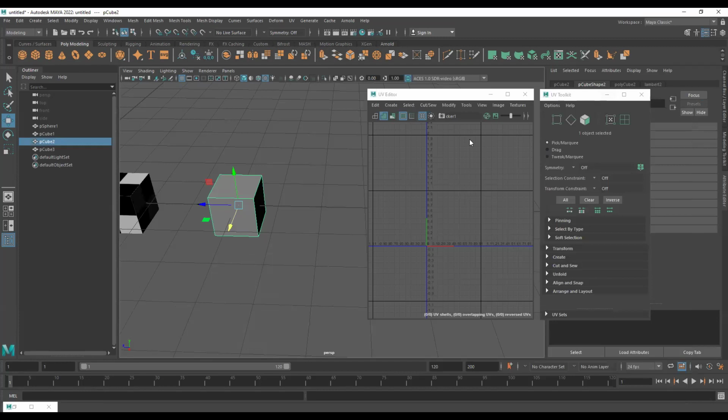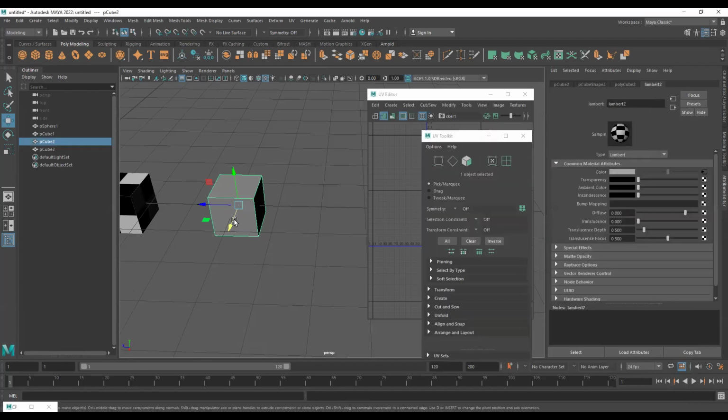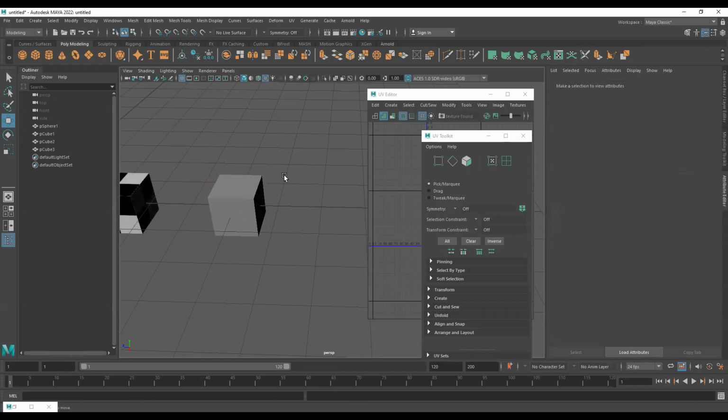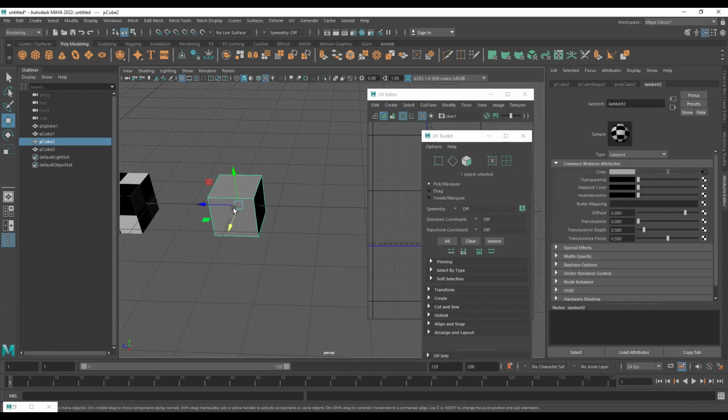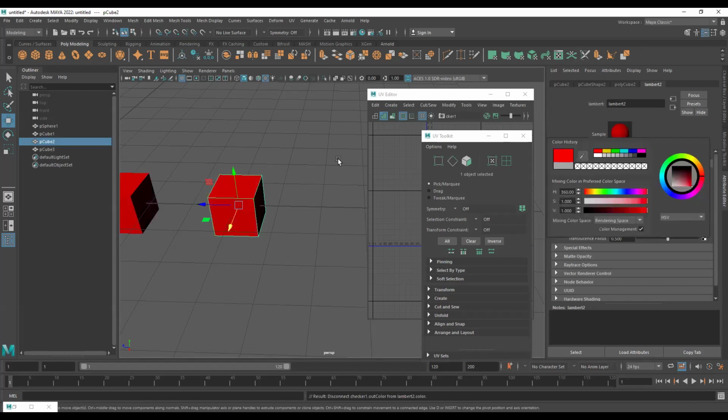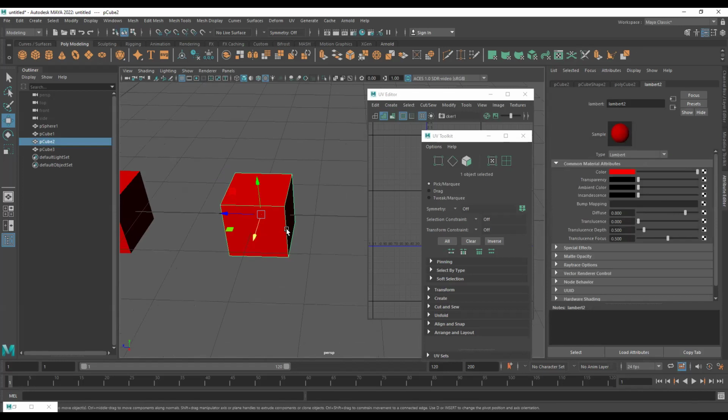Are you sure there is no material? No, you can see that the material is assigned to the selected object, of course, but we don't have any UV. So without UV, you cannot see the textures. For example, if I increase the transparency, you can see this object also getting transparent, isn't it? But why is the texture not applied? Because UV is not there. Only you can see the color. So break this, change the color. It will reflect. Color is fine.